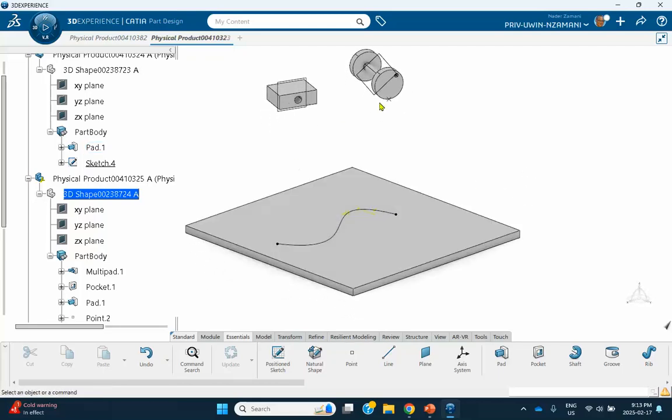Next, now remember, what you need to do is bring this wheel down and put it on that path. In order for us to have a roll curve joint, the boundary of the wheel, this circle here, must be tangent to that curve. It has to be.